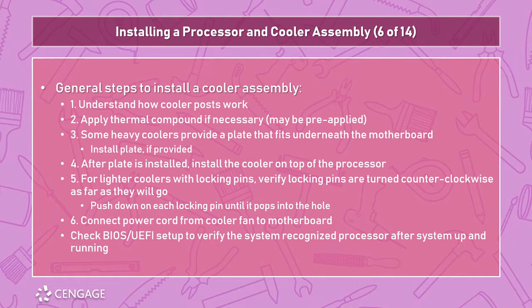Once you've put the thermal compound down, the thermal compound paste, which may be pre-applied, you may have to peel off a little plastic sheet to expose it. Make sure that it is down firmly and that you do not move it after that point. You don't want to smear it around. Kind of defeats the purpose.